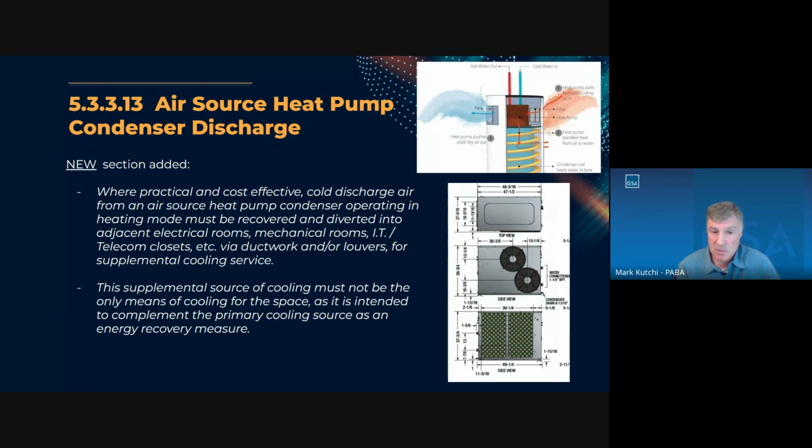Last point, though, it's important that the supplemental source of cooling must not be the only means of cooling. So these rooms will still have to be provided with cooling from the typical HVAC unit, but we'd like to be able to use this, what could be called waste cooling, to save as much energy as possible.